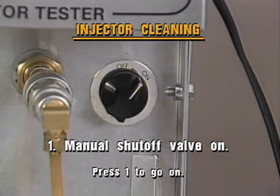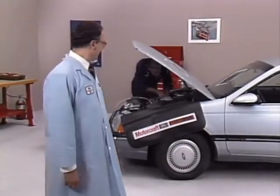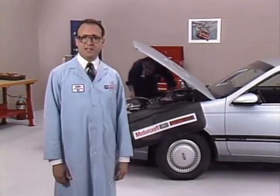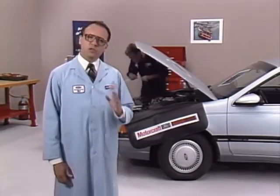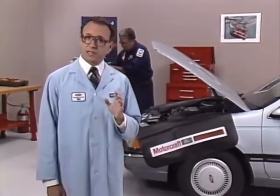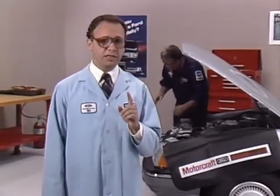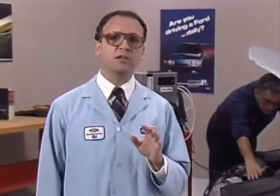Time to review injector cleaning. Press 1 on the controller to go on. Well, that completes fuel injector cleaning on the vehicle. We clean the fuel injectors right after testing, which is the way you'll most often do it. If, however, you must connect the tester cleaner to the vehicle before you clean the injectors, the hookup procedure is very similar to the one we did earlier for testing the injectors on the vehicle.